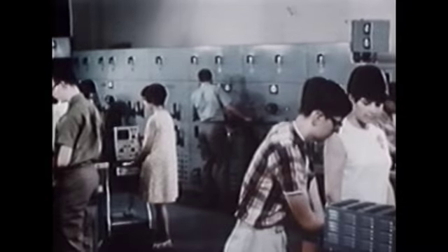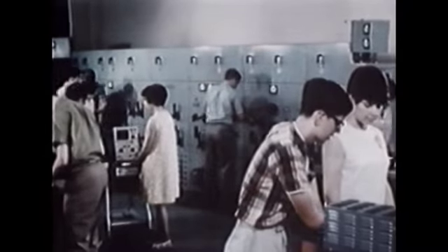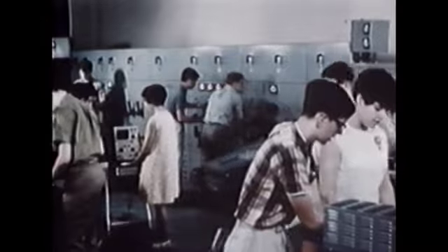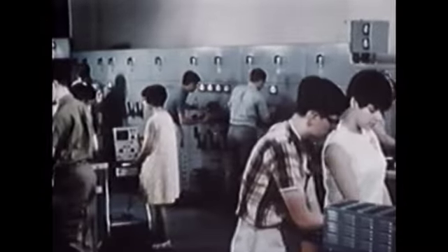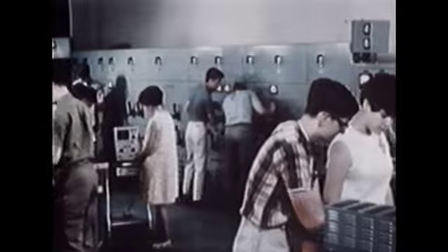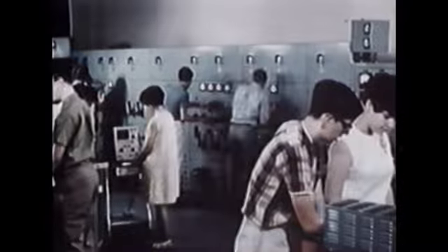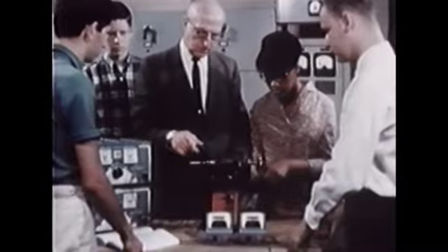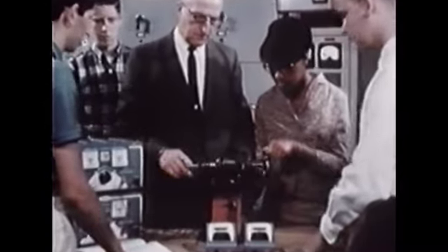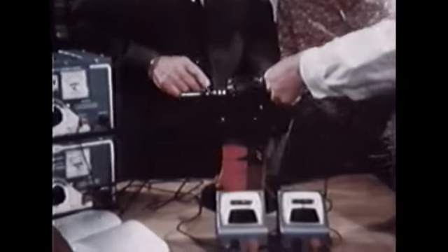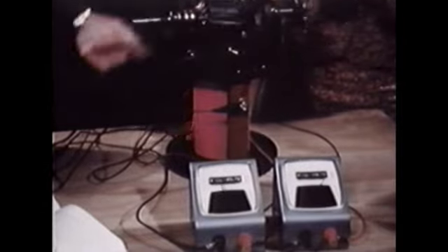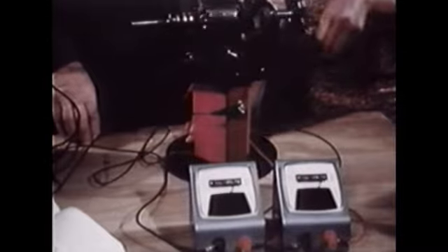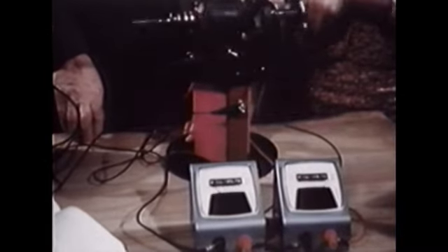Today, we are using staggering amounts of electric power. And as you continue to learn more about modern technology, you will find the basic concepts of current generation are of major importance. In review, let's look at a special generator which has an armature with both slip rings and a commutator. When connected to the slip rings, the voltmeter indicates alternating current is being generated as the armature is rotated. When connected to the commutator, a flow of direct current is indicated.